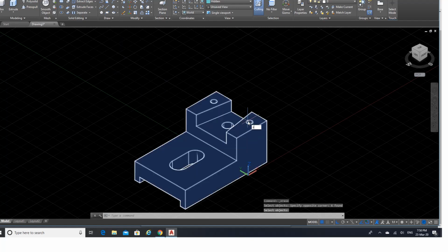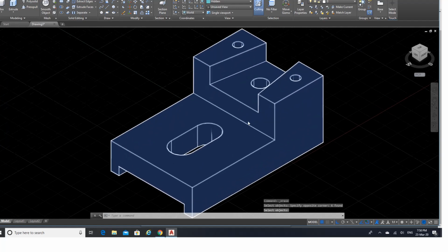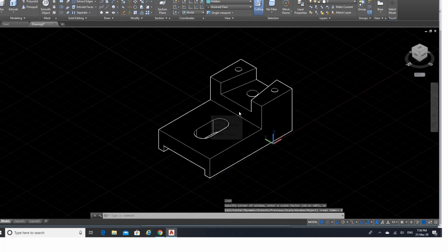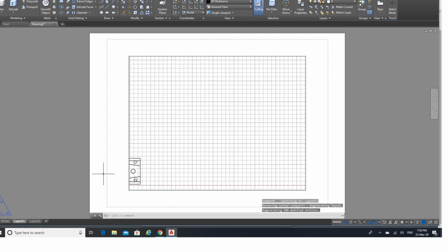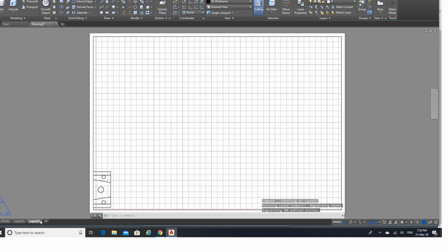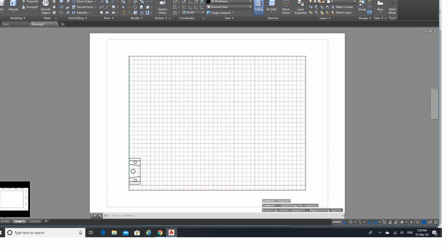Alhamdulillah. So now Z enter, E enter. See, everything is there. Zoom extends. So now we are there. Your drawing is ready. Now let's just go to layout view. So your drawing is shown somewhere there, and then if I go to this layout, it is shown somewhere there. No problems. Anywhere let it be there. So let me just go to layout 1.